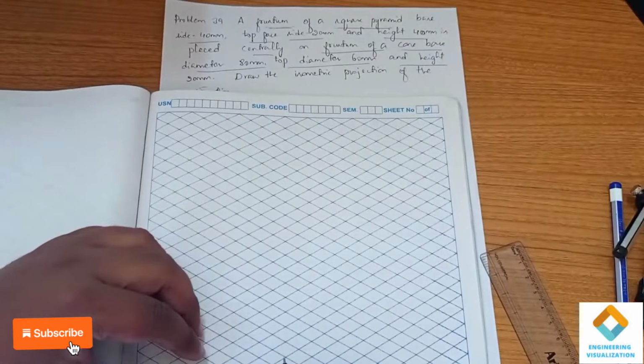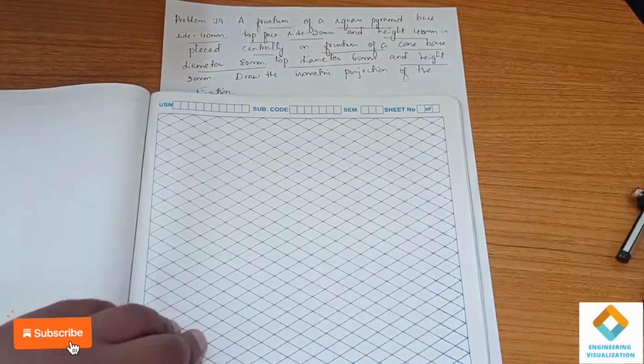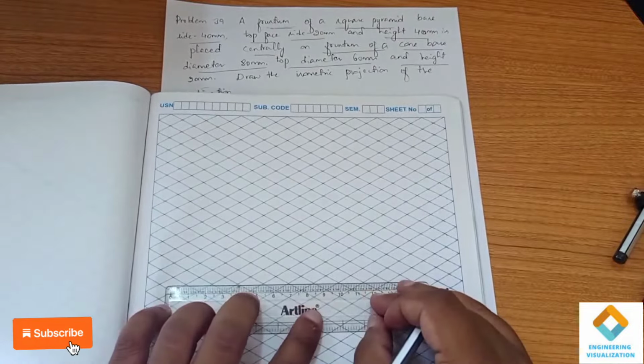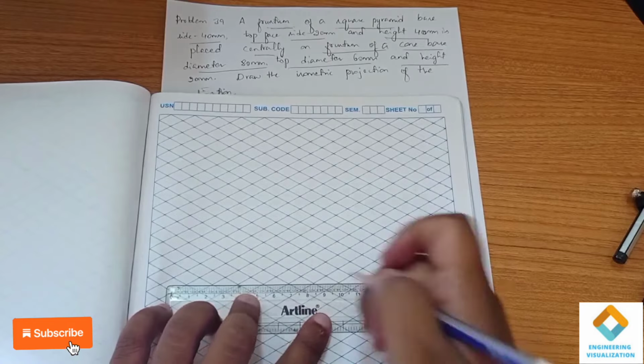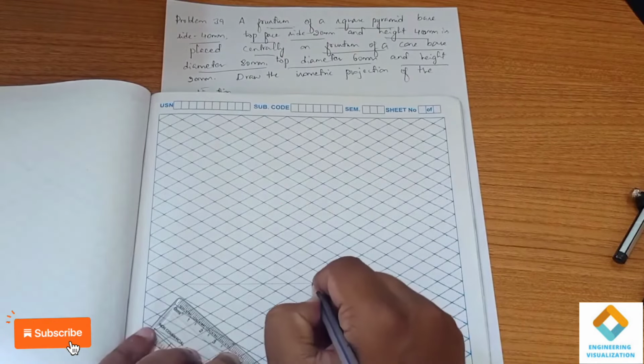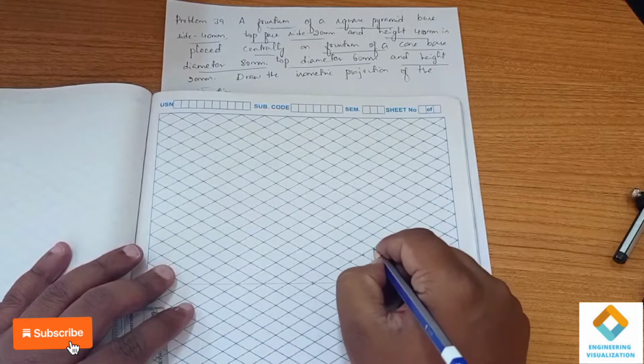In this, first we have to construct the frustum of the cone. They have given base diameter 80, so for that we have to construct the box. First I am taking a reference line here. So count 8 boxes.